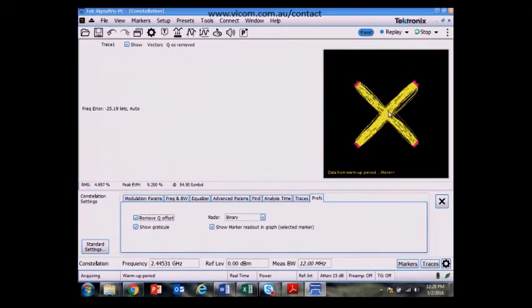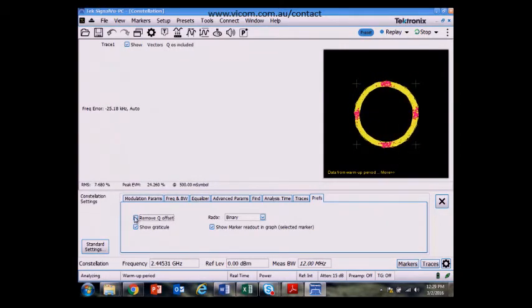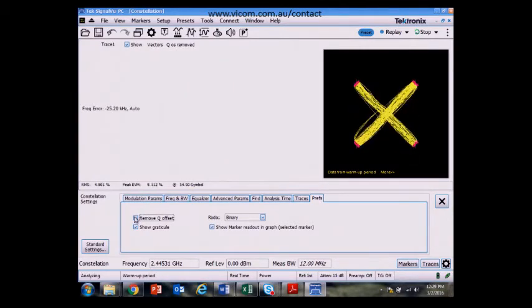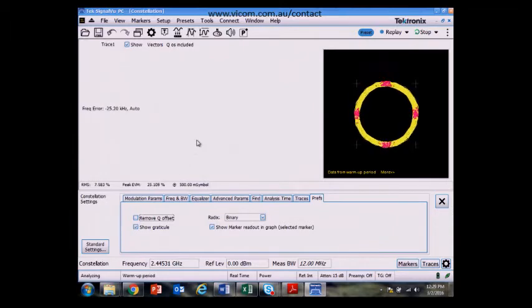One of the advantages of using a ZigBee device is I physically, in reality, don't have the zero crossings, but it makes it difficult to display this abstract implementation of ZigBee signals in the constellation diagram. So you can look at this either way, either with the constellation diagram showing up at the expected points or without the Q offset removed, that shows physically how the signal is really being transmitted, avoiding the zero crossings. It's a technique that's used to help save on battery life for ZigBee devices.